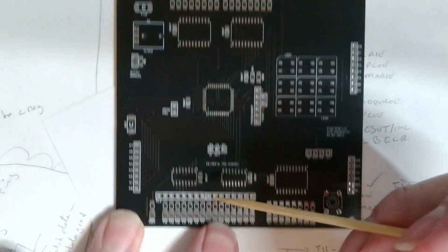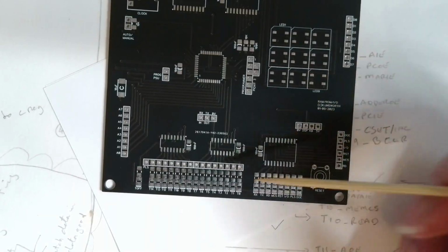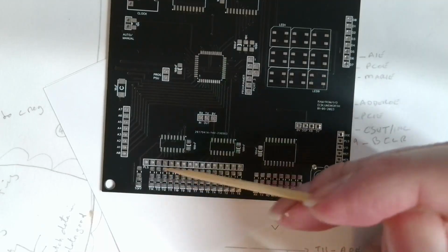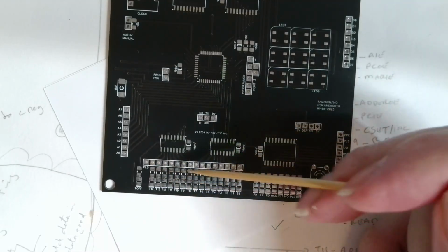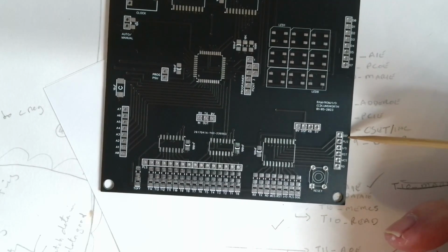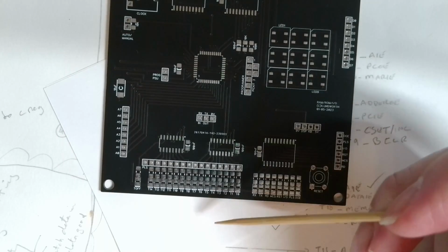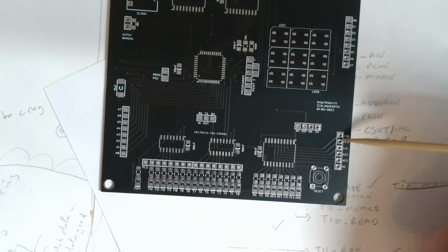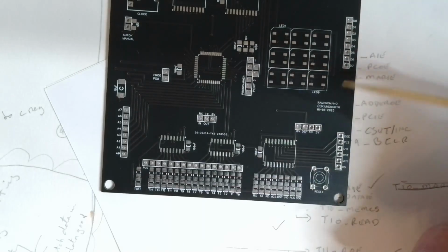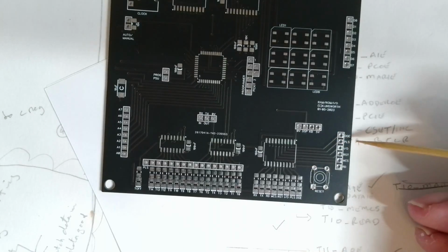These signals here, they feed off the bottom and across to the demultiplexer board and the instruction decoder where they're used. And the pulse signal is used on a couple of the instruction decoders as well, so that was fed that way. And so the control signals here, we've got data output enable. That's basically your read signal. There's your pulse going out here as well. The pulse goes out in 2 places. This one goes to the instruction decoder. This pulse goes up the control line to the registers, etc. on the main CPU. It's the same signal, just fed out in 2 places.